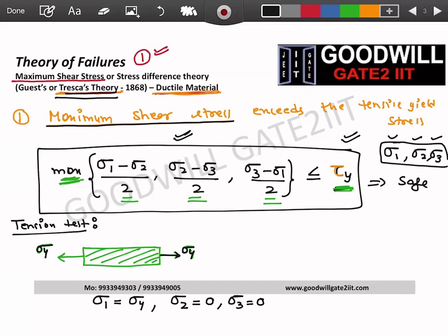So you took and you got your three principal stresses. So Punesh, I have given you a bar and you have applied a normal load to it. Can I say there will be one stress in this direction, which is nothing but sigma y? There is no stress in this direction, right? And these are principal stresses because there are no shear stresses. Agreed, Punesh? What are principal stresses? Principal stresses are stresses when there are no shear stresses. So whatever stresses I have are my principal stresses. And because it is a pure tension test, I have stress only in one direction.